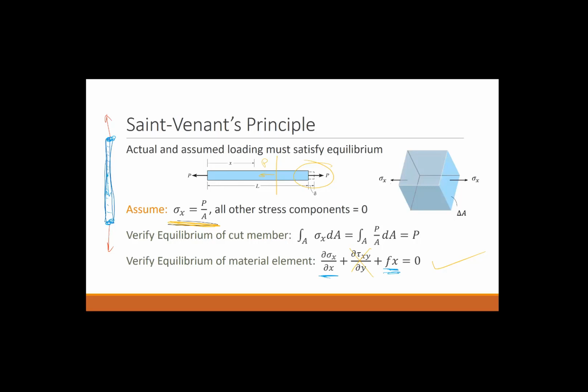that grows as you go up the object. So at the top, you have the whole weight pulling down on it. At the bottom, you have none, and everywhere in between, it's dependent on its location, linearly increasing. And so the point is, this term here becomes a linear function of x. So you take the derivative and you get a constant that's going to knock out this Fx term. It's not something you need to spend a lot of time worrying about, but I just want you to keep in mind what's really happening.